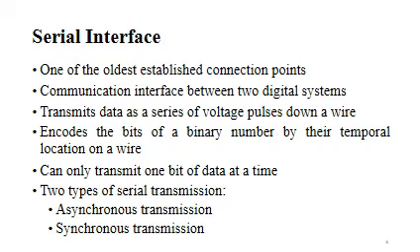We distinguish two types of serial transmission depending on the clock and data synchronization, that is, synchronous transmission and asynchronous transmission. In both transmission types, serially sent data are formatted in frames with fixed structures and lengths.